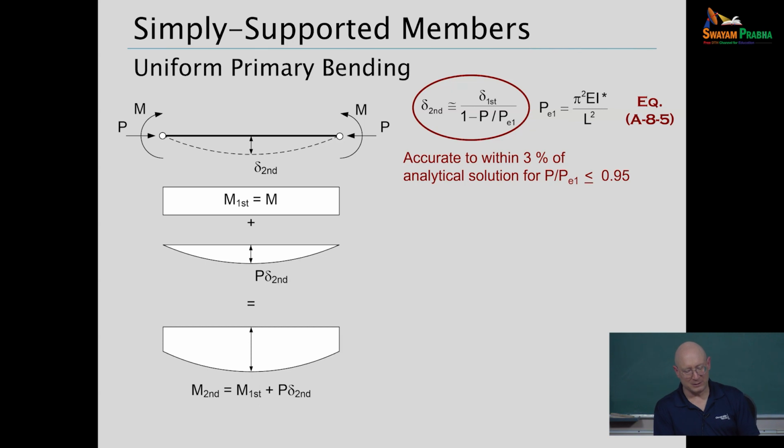And the result of this, you can get this from a geometric nonlinear analysis if you're discussing it from a finite element perspective, or you can say you're doing a second order analysis, which means equilibrium in the deformed geometry, right? You're evaluating equilibrium in the deformed geometry.